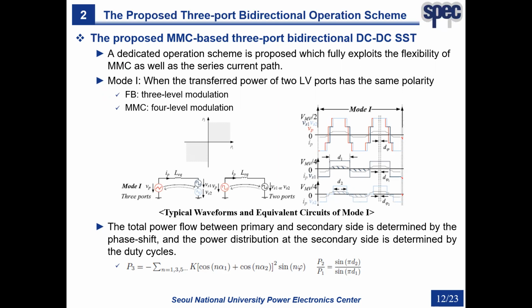Two operation modes are designed based on the power polarities of the two LVDC ports, and the power characteristics are analyzed, which resembles that of a 2-port DC-DC SST, and thus can achieve simplified power control. Now let's take a closer look at how the operation modes are designed.